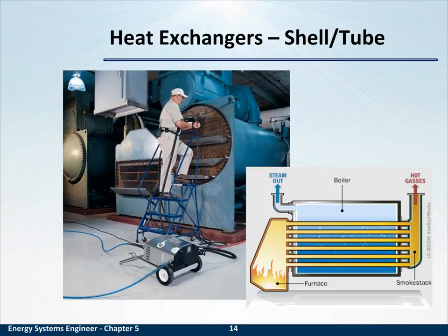This configuration of a large shell filled with dozens, hundreds, thousands of tubes is a very efficient way to do heat exchange, where these tubes are surrounded on the outside of the tubes by one liquid with another liquid running inside the tubes. Just looking at this picture, you can imagine the incredible surface area for contact, i.e. heat exchange, in this shell and tube heat exchanger.